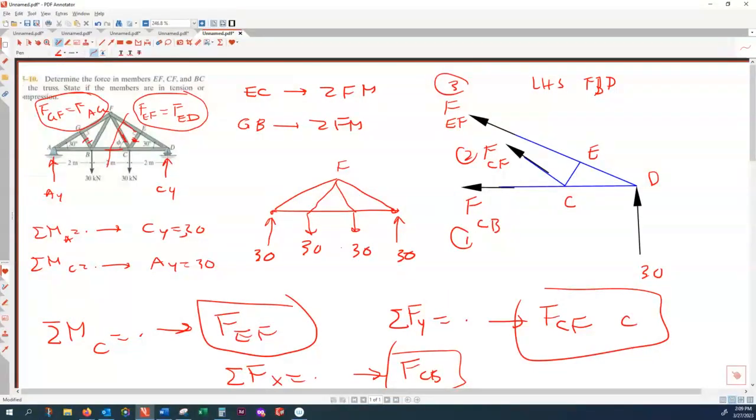And the feature of that is a free body diagram from method of section. It splits the structure in two pieces. You have to choose which split is the best one to start with. And it can handle three unknowns because by making a section, generally speaking, you end up with a rigid body free body diagram. And rigid body has not only capacity to translate, also it has capacity to rotate, and it has three useful equations.